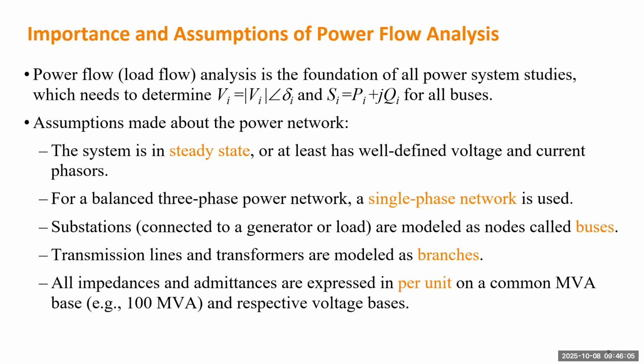Next, we want to make the calculation easier, especially for the convenience of coding. If you want to program power flow analysis in some software, we don't want to deal with physical units, whether kilovolt or volt, ampere or kiloampere, megawatt or kilowatt, right? So we don't want to deal with units. We want to convert everything to per unit. Then we need to choose a base. For power, we have to select a common base for the entire system.